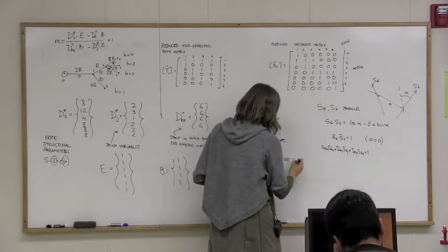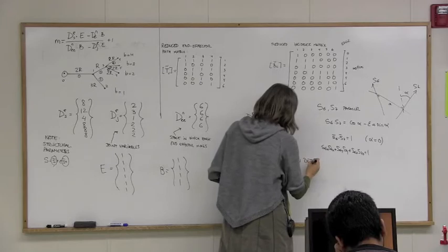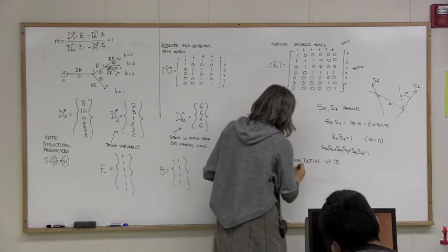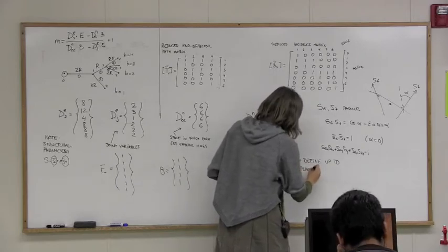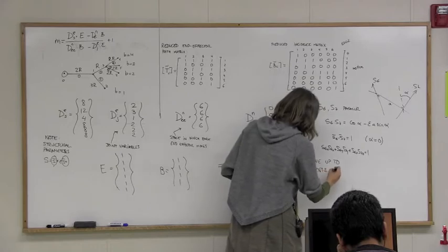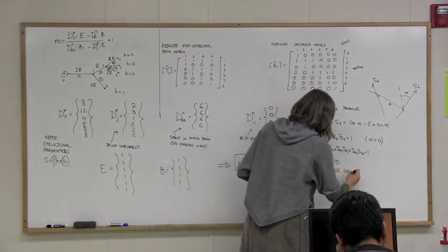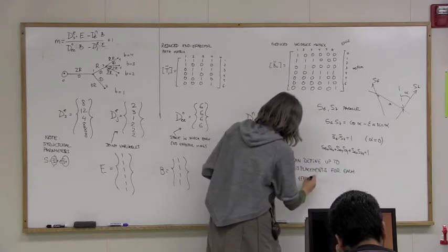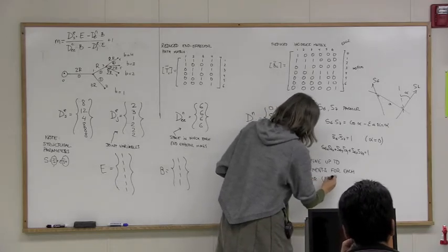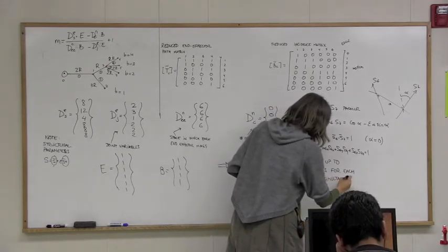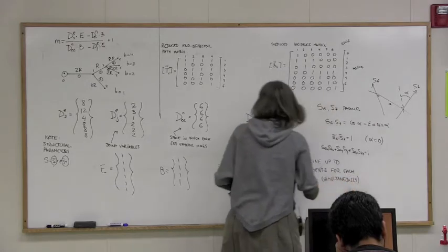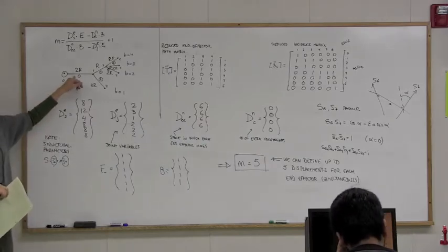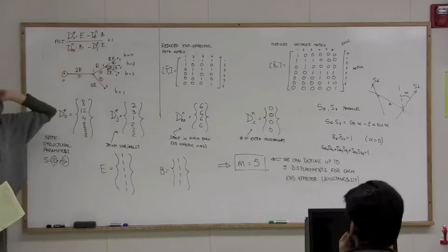we can define up to 5 displacements for each end effector. And that means simultaneously, okay? Why are they simultaneous? Because we have some common joints, okay? So once you have an angle for this joint, that is going to be the same for all of the end effectors, right?